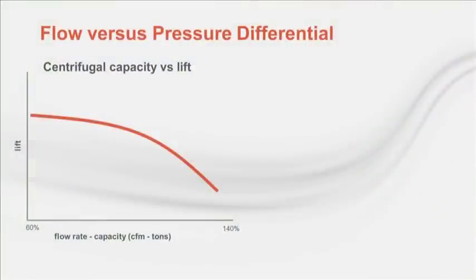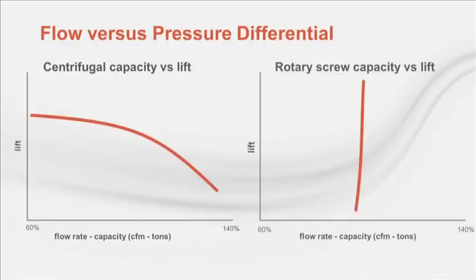For the purposes of these discussions, we're going to focus on rotary screw compressors. But before we get into the details of rotary screw compressors, let's take a closer look at one of the big differences in how the centrifugal compressor operates versus a rotary screw compressor. For a centrifugal compressor, without taking mechanical unloading into account, the flow, and in turn the capacity, would ride the curve as pressure differential, or chiller lift, conditions change. Again, this is without any unloading built in, which is nearly universal for centrifugal chiller applications. For a given rotary screw compressor, the volumetric capacity is not significantly affected by lift. It's a nearly vertical line. This is not to say that capacity, or more importantly, the efficiency of rotary screw compressors won't change with varying conditions. The point is that lift reduction has very different effects on the chiller, depending on the style of compressor being operated.